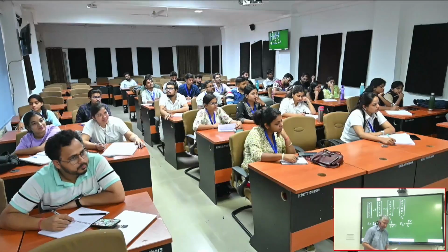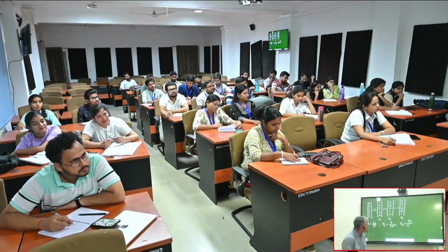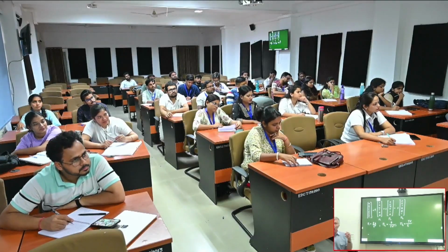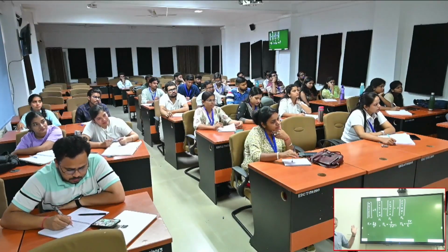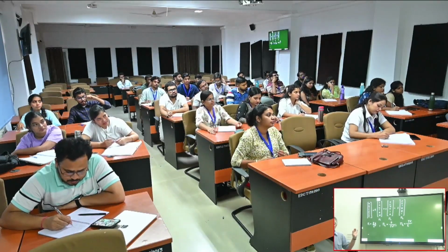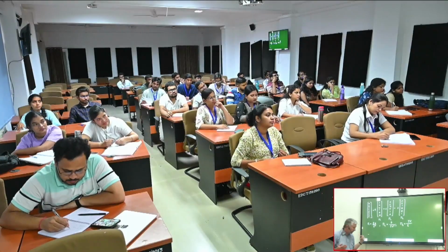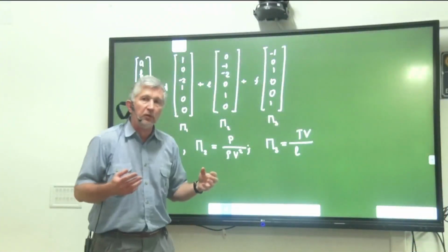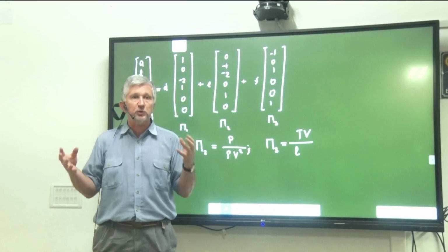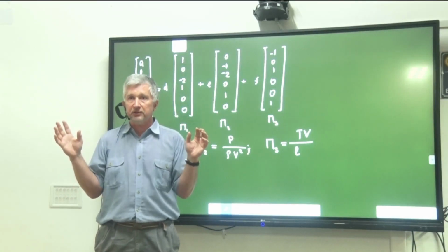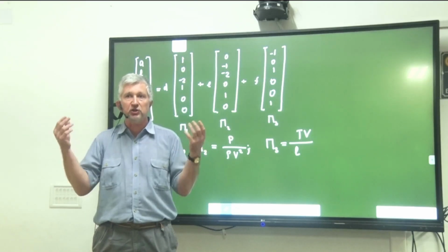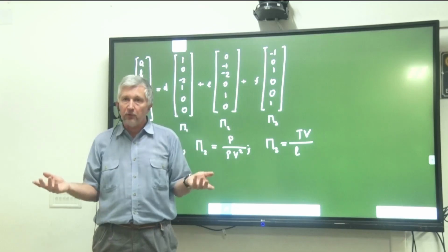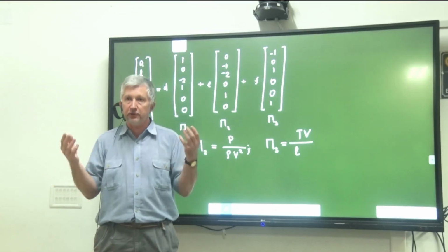So basically what we obtained here is the statement of how many non-dimensional groups we can have. We cannot have more than 3. Only 3. At most 3. Remember what we started with? We started with a system of equations which contained 6 different physical parameters. And then the question was, if we have 6 parameters and we change a couple of them, or just one of them, does it mean that we will have to work out the new solution from scratch?